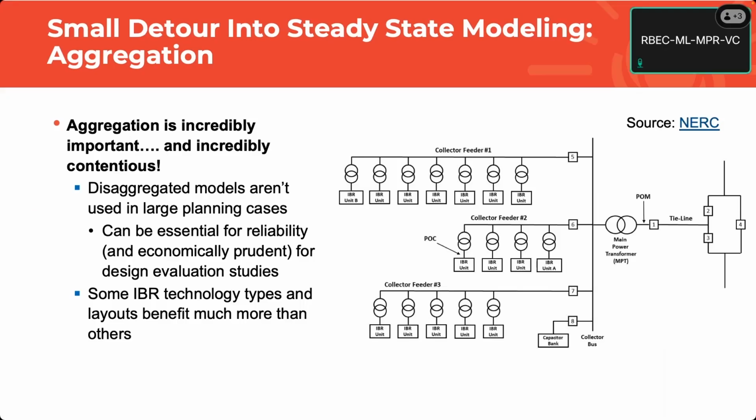So you may not see a huge difference between an aggregated and disaggregated PV plant, maybe a megavar, 1-2 megawatts, something like that. So not too big of a deal. But if you're right up against a power factor requirement of the utility, that could be expensive. 1 or 2 MVARs of cap at your site could be expensive. It may be cheaper to do a study like this.